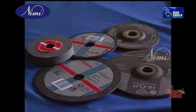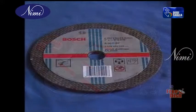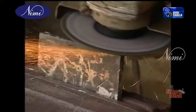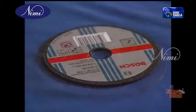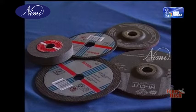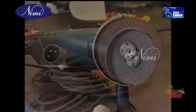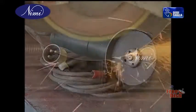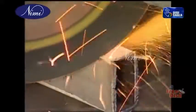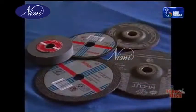These are some of the wheels and discs that we use in this machine. So, this is a typical grinding tool. The grinding wheels are made up of abrasives. This is a cut-off wheel used for cutting purposes and this is a grinding wheel, and both are 7-inch in diameter. The selection of the equipment depends on what you want to cut. Depending on the thickness, the RPM, the power in watts and so on, you can save time while cutting a huge amount of metal using the appropriate equipment.